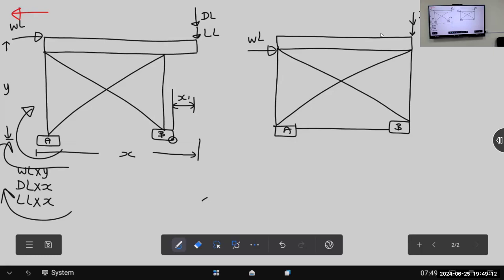Absolutely. Why? Because it is moment against moment for stability. The resultant is now the live load minus the wind load. In magnitude, the forces developing the moment are less. But who knows the direction of the wind? Nobody knows. The wind today from this direction, tomorrow from another. Correct or not? Nobody knows.